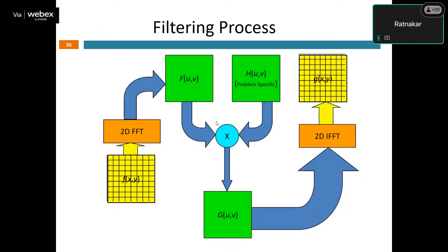That is very crucial for different applications. In order to highlight a particular frequency band, it is always advised to convert the whole image into its frequency representation, so that we can know which frequency bands are present and highlight them very easily. So we can use this filtering process in the frequency domain to identify and highlight the corresponding frequency band.